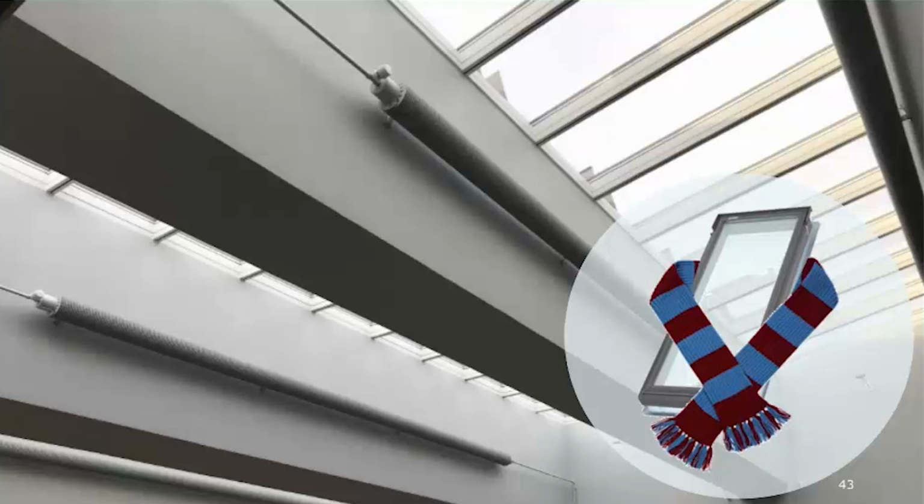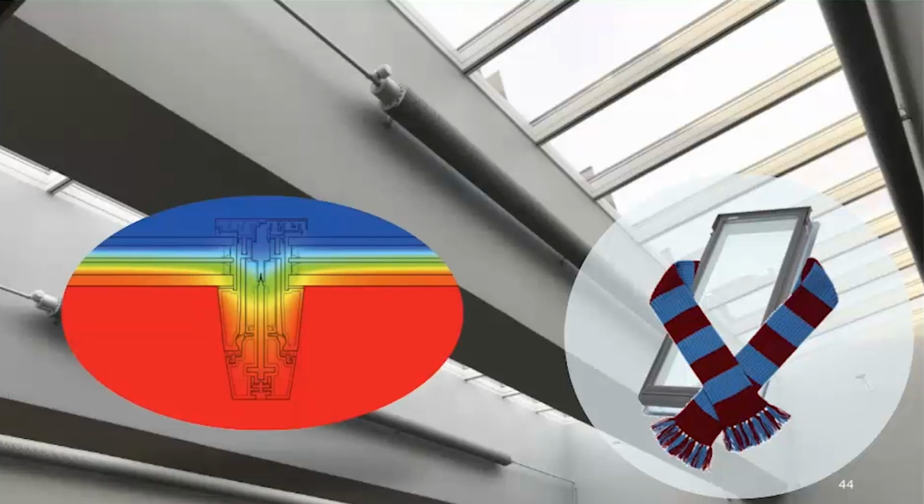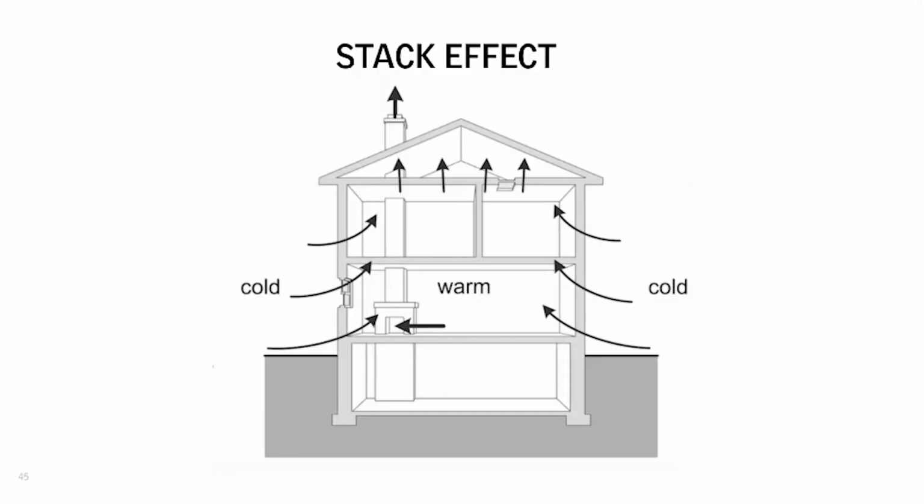The real challenge for us at this stage, when skylights are getting so energy efficient, is that if you can handle much colder temperatures and keep that inside surface above, say, 7 degrees, as in the example I showed, do you still need that heating source up by the windows? Because when we're thinking about energy, if you're applying heat up there, a lot of that heat's just going to be lost out the window. If you have a really high performance building, the location of your heating source becomes less important. So you might not need it near the skylights when you're using really good performing skylights.